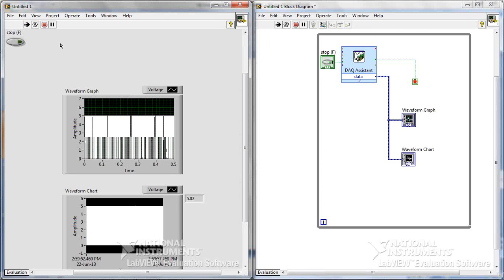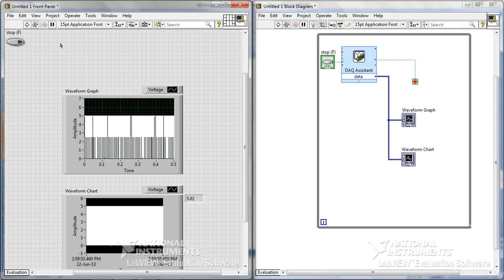And this is how you can acquire any sensor-related data from the external environment through a sensor, capturing whatever data back into your DAQ assistant. This is how you have to interact with any kind of sensor, provided you need to know the proper working voltage. If you're sure of your working voltage, you can just go on with your DAQ assistant. If it doesn't match, it is better not to connect to that. The worst part is that if the working voltage shoots above the rated voltage, there is a chance of your DAQ getting spoiled.